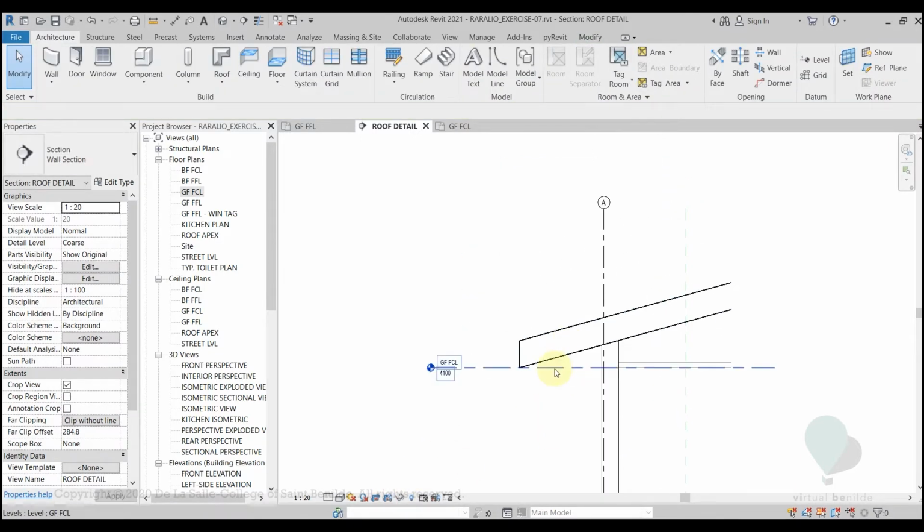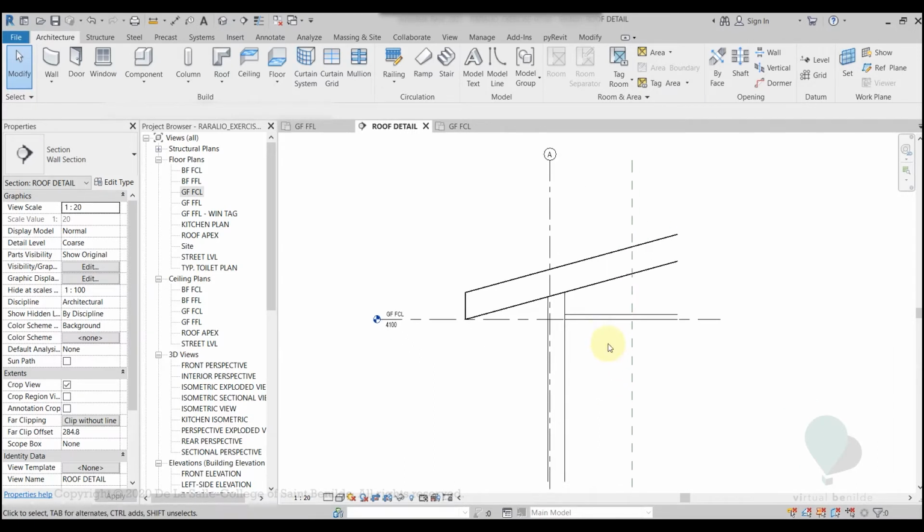All right, so in Revit, most of the time, when we create detail drawings, we create them from a section or an existing section created from the model, and then we overlay it with 2D drawings, 2D lines, and maybe replace them with hatch patterns, or add additional line work to show the connections, show the details.